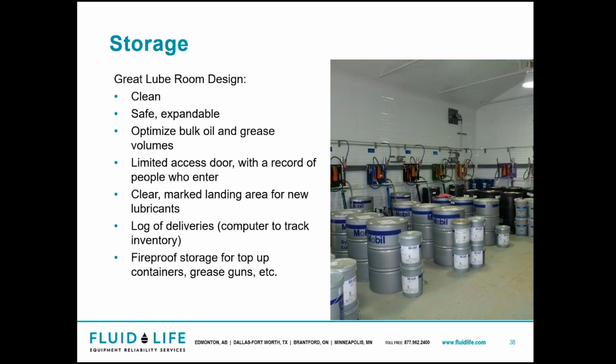And quick connects. The quick connects would not connect to different lubricants or different components. So all these little steps make contamination control a big part of your loop program. Now, I know some of you are probably further along in the oil journey, and others are in the infancy stages. But this is one of the primary things I'm always going to recommend: filtering and color coding.